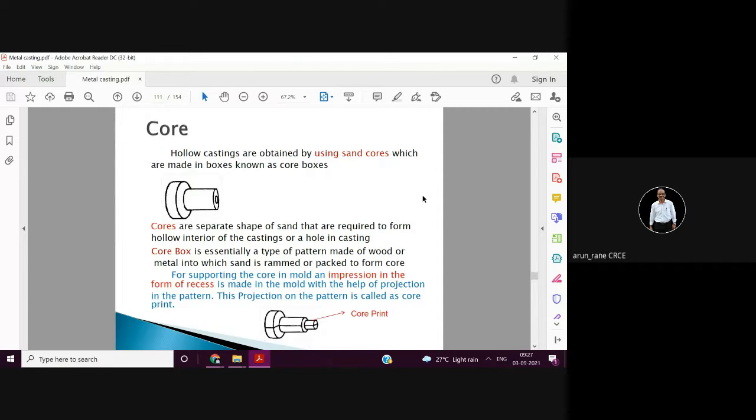You can also use the process called chemical dipping, in which the castings are kept in chemicals, so the foreign particles or the external particles surrounding the surface of the workpiece can be eroded. But this is not useful for very rough castings.